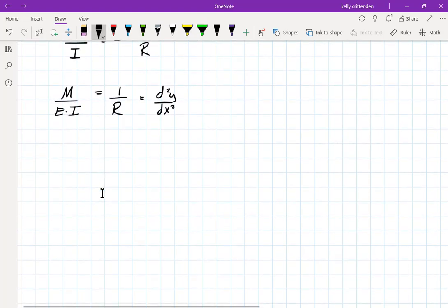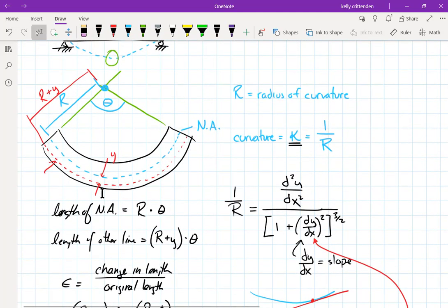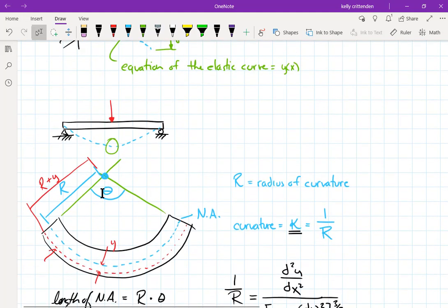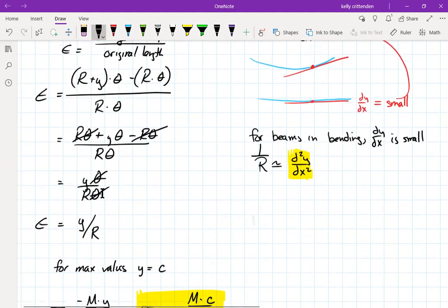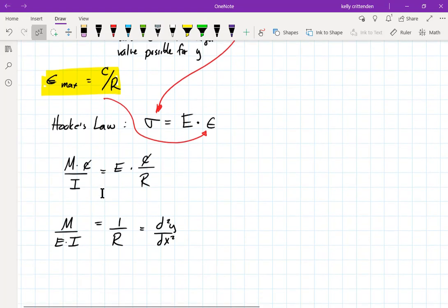So what I have then, this moment, now the way I generated this beam, this flex here, this nice curve, is I just put one force on here, P or whatever it might be. What we've developed here would be the equation of the elastic curve for a given bending moment. So remember last week, or maybe it was 2 weeks ago, you were doing the thing where you develop an equation for m of x at any point in a beam. So every time m of x would change, the equation for m, then you would also need to change it here.